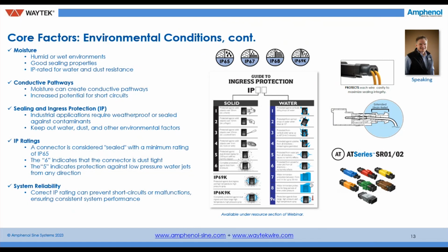So those conductive pathways: moisture can create conductive pathways. Sealing, the thermoplastic materials that we're using, absolutely critical to mitigate that. As we talked about sealing and ingress protection, these industrial and automotive applications increasingly are going to require weatherproof or sealed connection systems against all manners of contaminants.